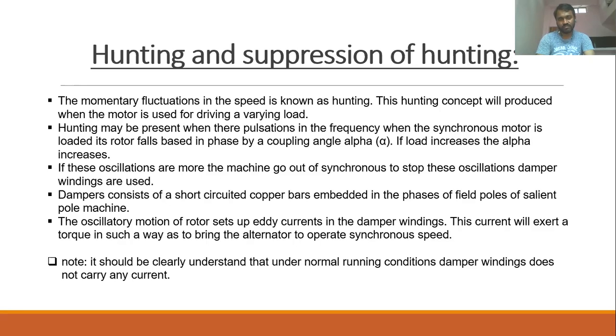It will be somewhere 10 to 15 degrees. We should see to it that the coupling angle does not cross a certain limit. If not, the machine will become unstable, and the rotor completely falls back. And here, how to overcome this?